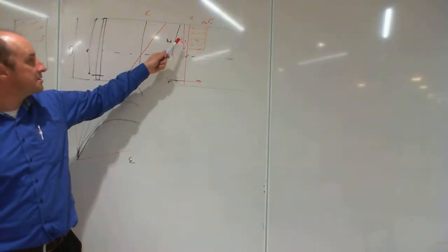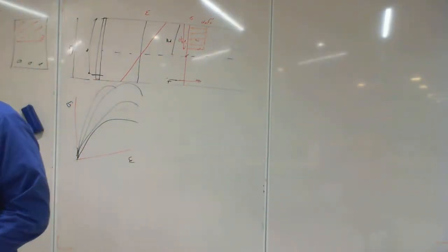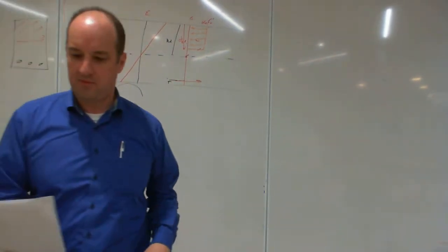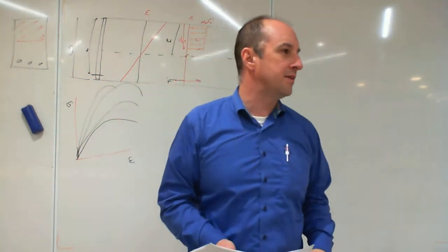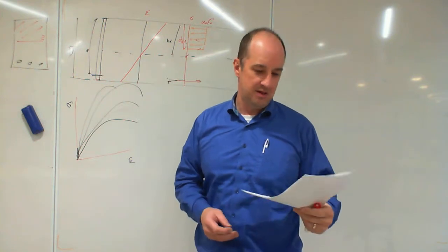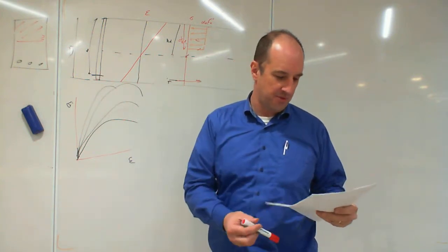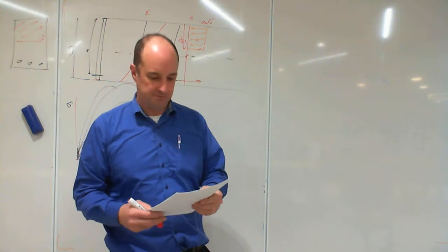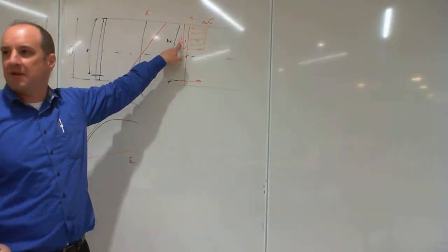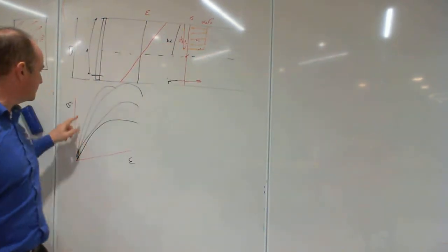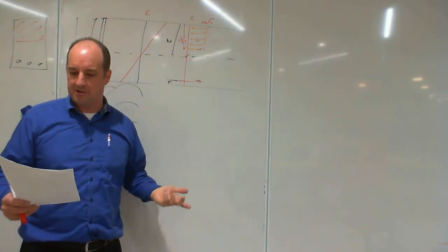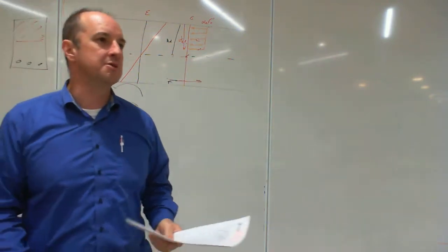And when you do the numbers, alpha 2 comes from the code. It comes from clause 8.1.3, and it's got a little formula in there. The formula is different whether you're talking about the current version of the code or the previous 2009 version. But clause 8.1.3 has it, and it's about 0.85. And gamma also has an equation. It depends on the strength of the concrete because of these different shaped curves. And gamma is approximately between 0.67 and 0.92. And that's also in clause 8.1.3.